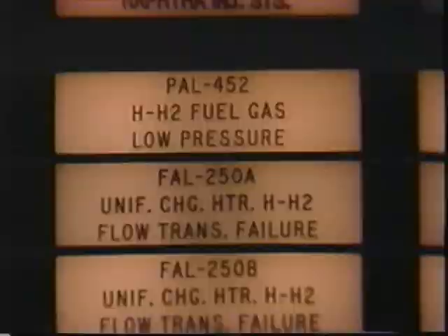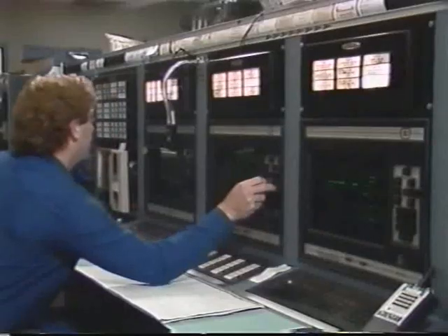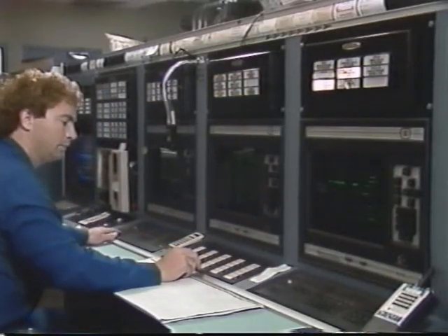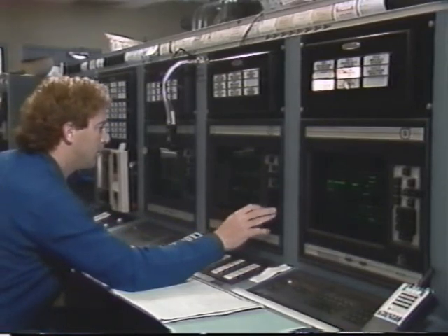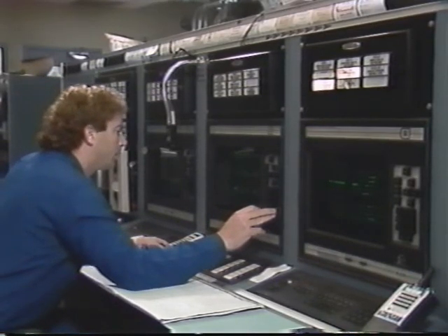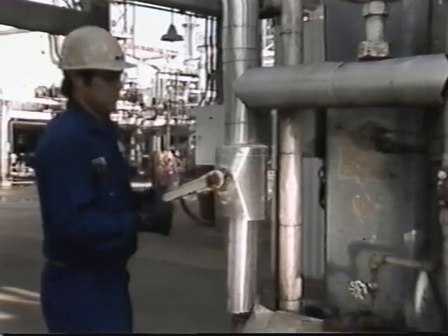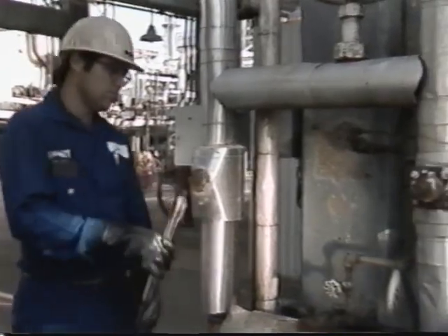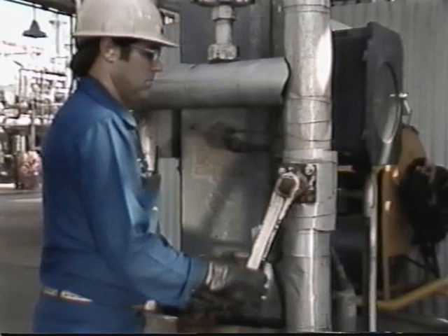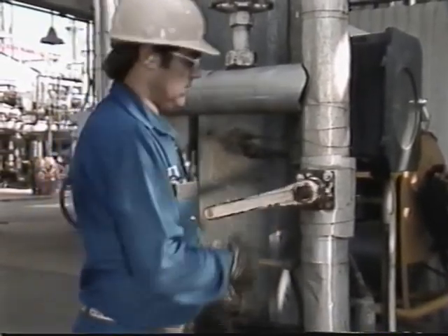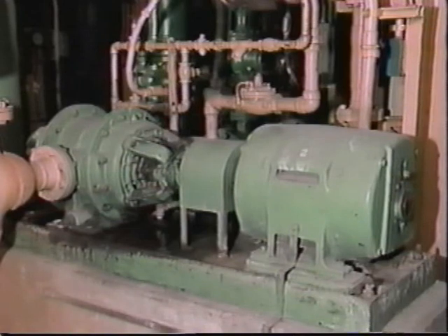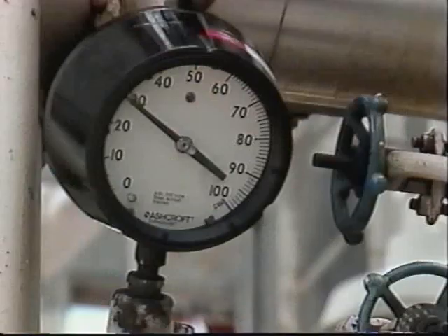For some problems, you may have to initiate an emergency shutdown right away. Or, if conditions allow, you may be able to keep operating, but you might have to switch from automatic to manual control to investigate the problem. Another preventive measure that's sometimes necessary is to bypass a piece of equipment or part of the process while the problem is being looked into. Standby equipment may need to be used during troubleshooting.